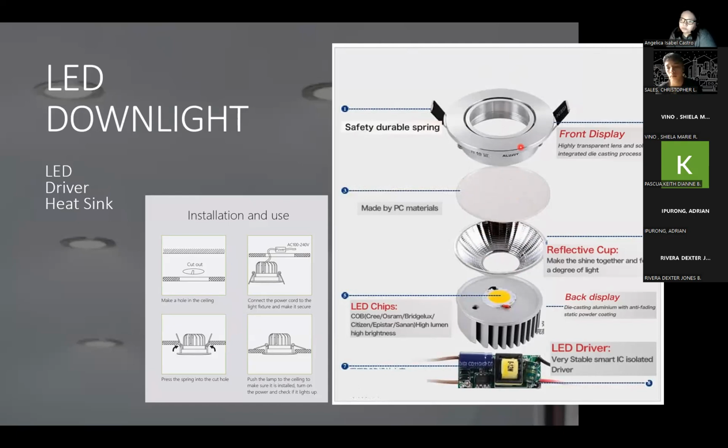One thing I've learned over the past years that I've been working is that pag LED yung ilaw, mas effective if yung finish ng reflector ay yung mga sandblasted finish. Kasi itong mga diamond finish, yung mga ganito na maraming shiny something, this works better with CFL. I don't know if anyone has noticed, pero that's something I've noticed with the installations or the lighting fixtures that I do now. Any question with regards to your downlight, LED downlight?